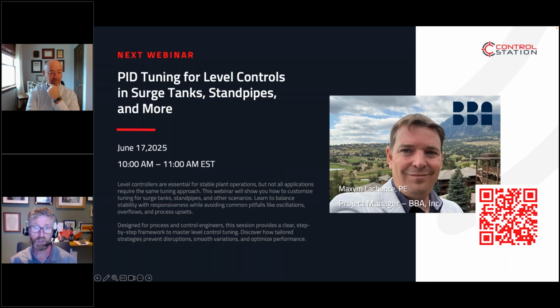How do you fix stiction? You don't tune your way out of it. You go and fix the mechanical problems. That's the solution, the root cause. But as we mentioned, there are ways to mitigate it to get you to the time where you can root cause it.